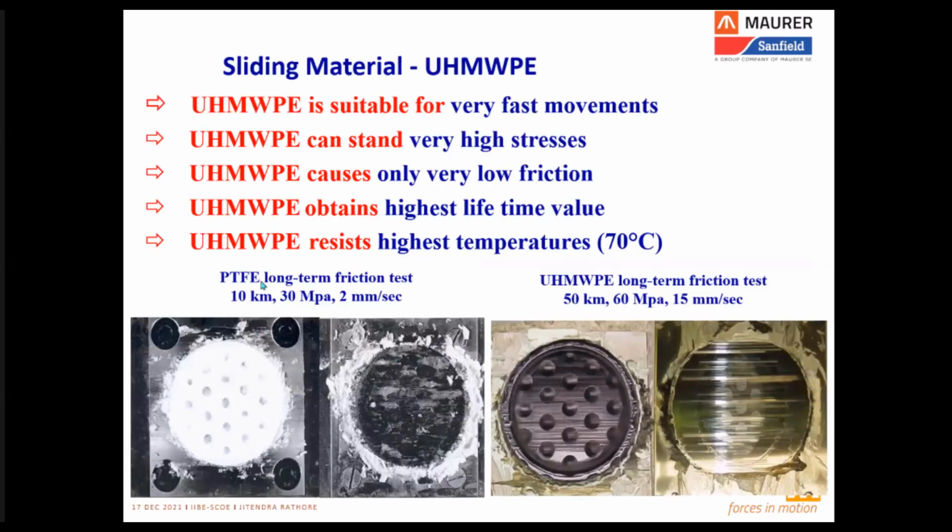So when we have a side-by-side comparison of PTFE with this UHMWPE, wherein the sliding path is 5 times, the stress or load bearing ability is double, and the high velocity movement which it can support is about 7 times, it is not a genius task to conclude that this material is suitable for fast movements. It can take very high loads and stresses, offers a low value of friction, and thus offers the highest lifetime.